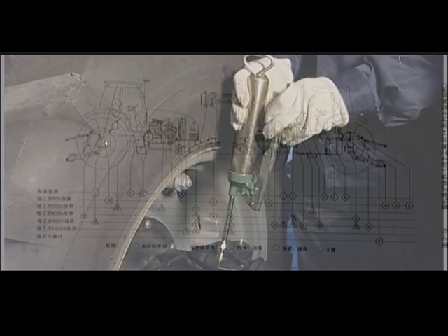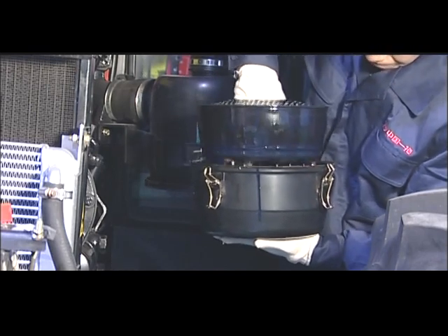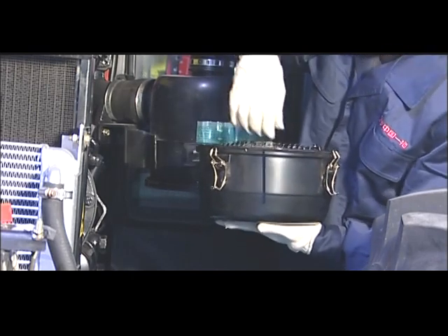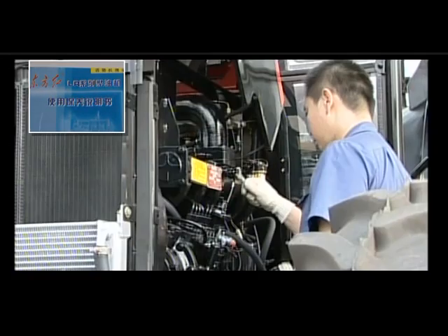50 hours technical maintenance. Complete the all work of 8 to 10 hours technical maintenance. Refill with lube grease based on tractor maintenance diagrams. Check the oil level of the air filter if reached to the marked position or not. Maintain the diesel engine based on the engine service manual.